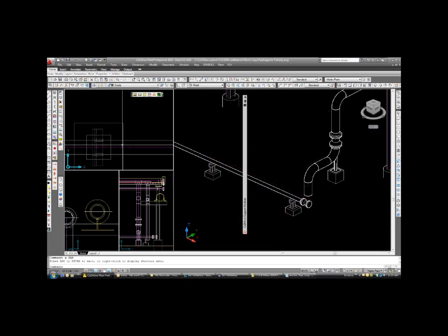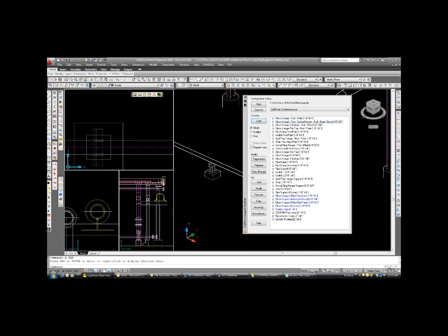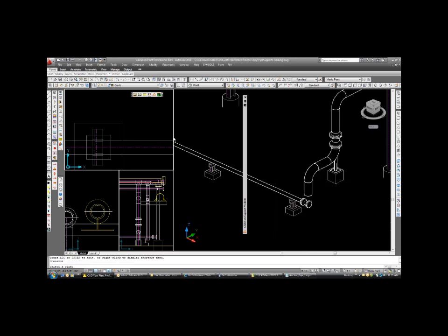So let's go here, go back to our modeler. We'll select multiple. I'll try to detect steel and see if it works. And we're going to select the U-bolts. But once again, this time I'll hit insert. And it's going to ask me to select a pipe. So in the plan view, I'm going to select the opposite end of the pipe here. Start point, I'm going to pick the nearest, because I'm not going to be too accurate at this point, about where I think that U-bolt should go.